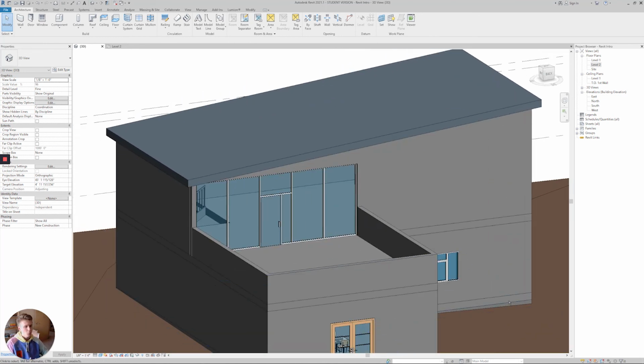So to recap, we went over how curtain walls aren't structural, they should be embedded and cut into the wall that you were building in Revit. We learned how to edit the properties tab to give them grids and manually add mullions and grid lines to them, as well as adding mullions to them in the properties tab. And we worked on individually selecting a panel, switching the type of panel to a door rather than using a door placement in the architecture tab. And I hope that all of this can be helpful for you in your own projects in the future.